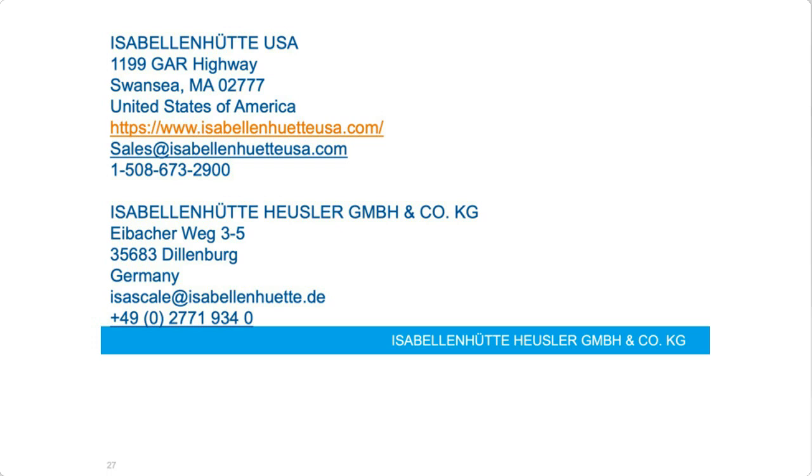So the cycle time for isolation monitoring in our product is set by standard to 100 milliseconds. It obviously depends a little bit on the product that you're looking at, but we basically chose for our product to offer a cycle time of 100 milliseconds.